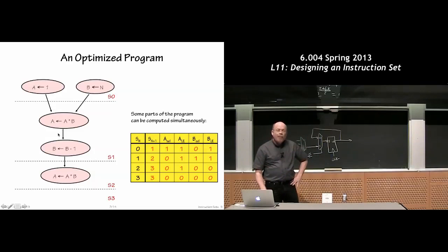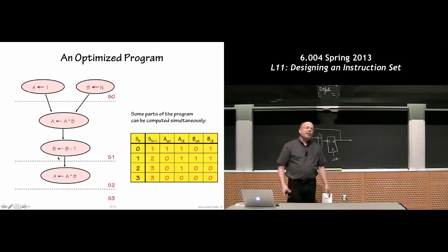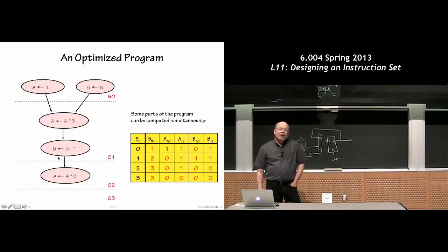And then this assignment operator is really saying, at the end of the cycle, please update the register with these newly computed values. And so this hardware actually works fine. I don't have to think of these as sequential operations. I can do them in parallel. And I've basically adjusted my table now to have one fewer state and combine some of these operations.